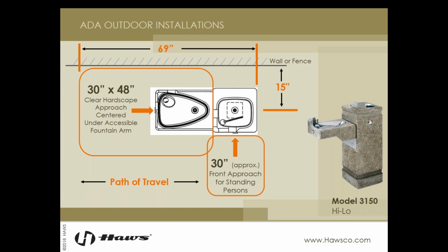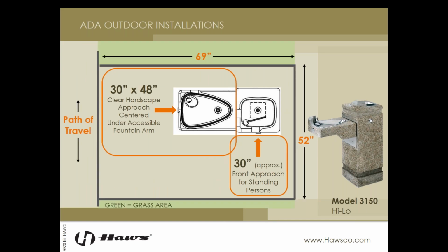Oh, and remember, there is no exception for outdoor fountains. In California, they would still require your 32 inches of floor space, especially if this was alcoved outdoors.